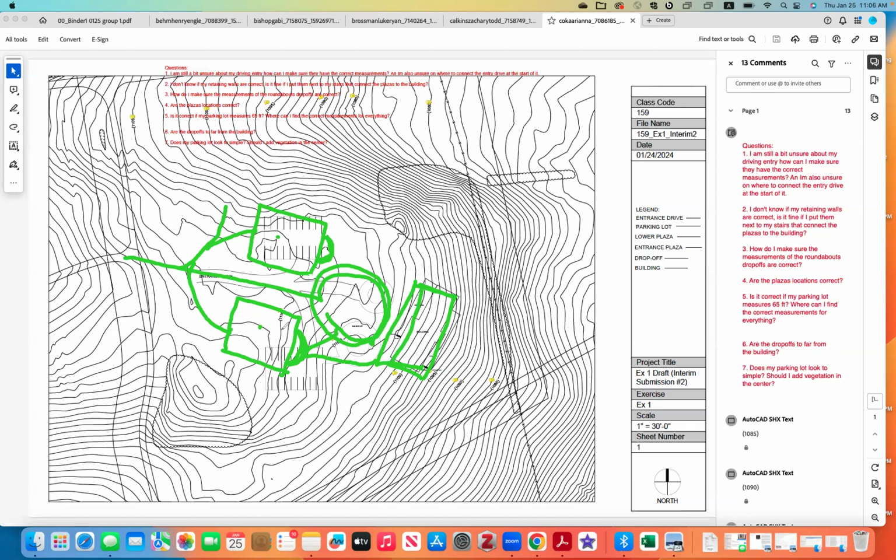My recommendation would be you first lay out these 2 individual parking lots, 10 parking stalls for each one, right? And add a drop-off area for both of them and try to place it in areas that are flat. I am intruding into the steep slope over here, so that's less ideal, okay? You would want to stay away from the steep areas here, keep 50 feet away from the vegetation.